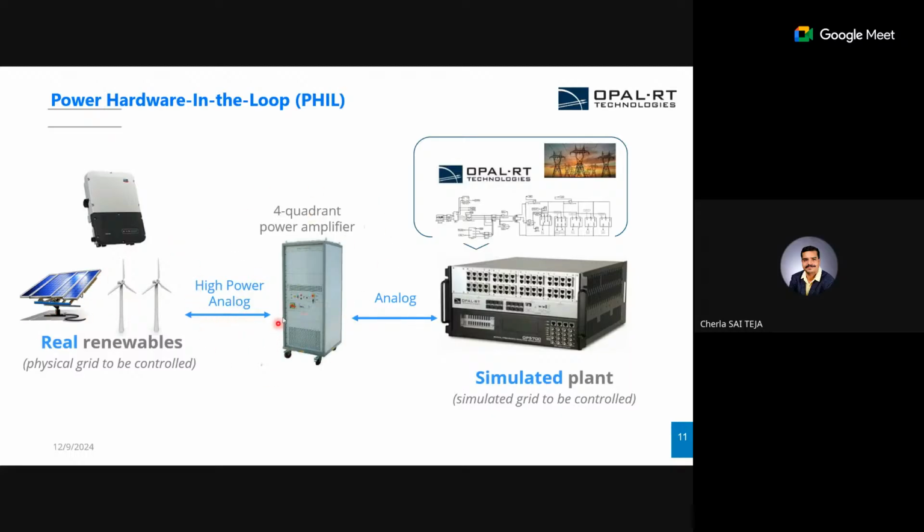In this way, along with the test of the external controller, we can verify the performance of this solar inverter, whether it is in accordance to the simulated plant or not, whether the responses from the simulated PV inverter and the real PV inverter are the same or not. We can test in a safer environment, then proceed to commissioning this real controller into the real PV farm.